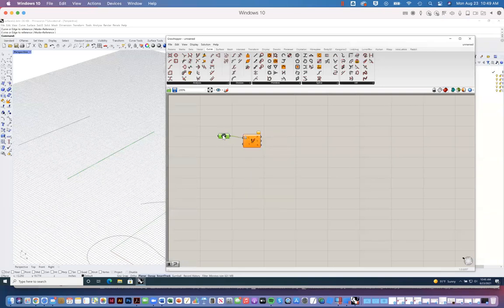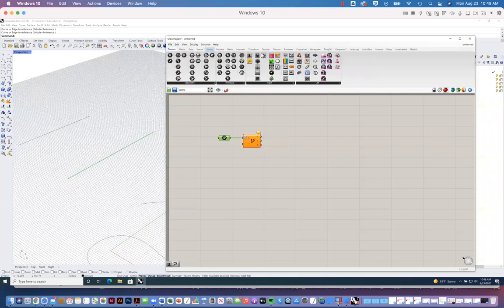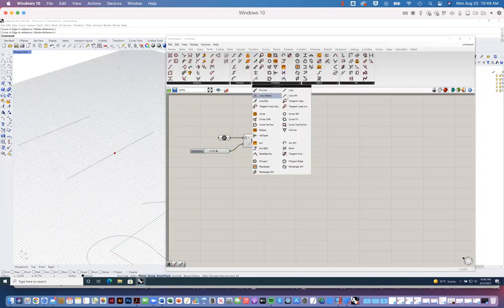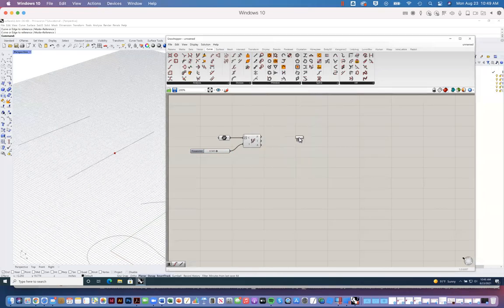I'm going to reparameterize this curve, right? I'm going to give it an address, like a street address along a street, right? Go from 0 all the way to 1. I'm basically placing a point on this curve, right? If I want to go halfway, like at the midpoint, I can double click. I can say 0.5. If I want the end, I can go to 1, or at the other end, I can go to 0. All right, and now I'm going to draw a line, just like I sketched, from this point. Let's say start point, direction, and length, right? So there are lots of different ways to make a line,